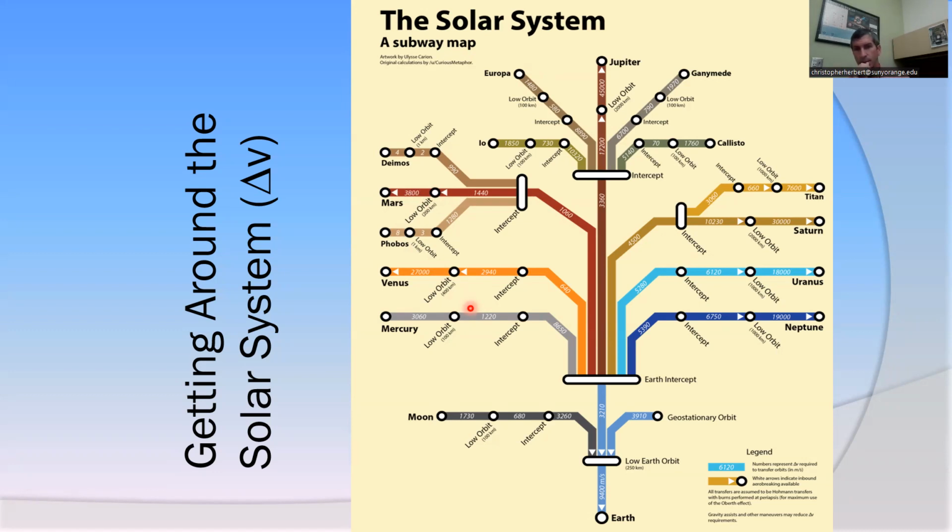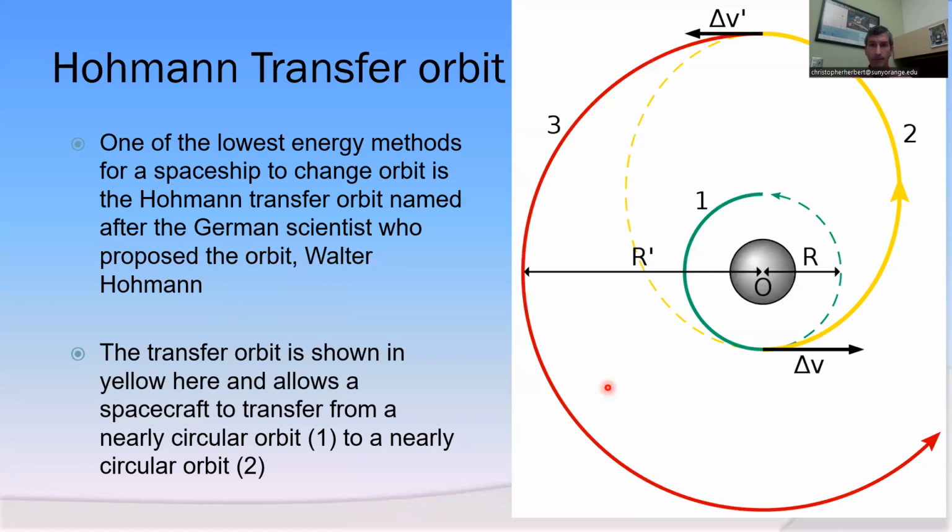It's important to state right here that once we get into low Earth orbit, any additional delta V that we have results in an exponentially larger amount of mass. So, just because this seems like the largest part that we pay, as we put more delta V into the system, the overall cost in terms of fuel from initial to final is going to result in an exponential growth in the amount of fuel that I need.